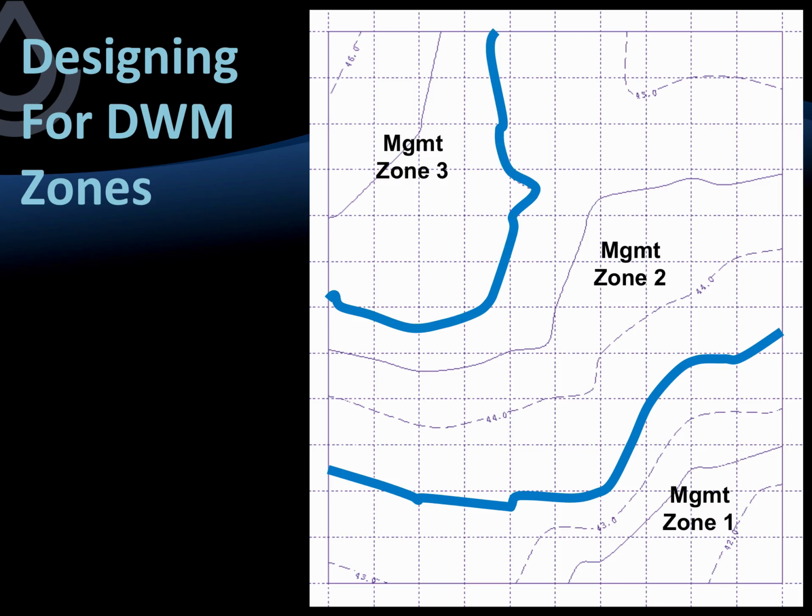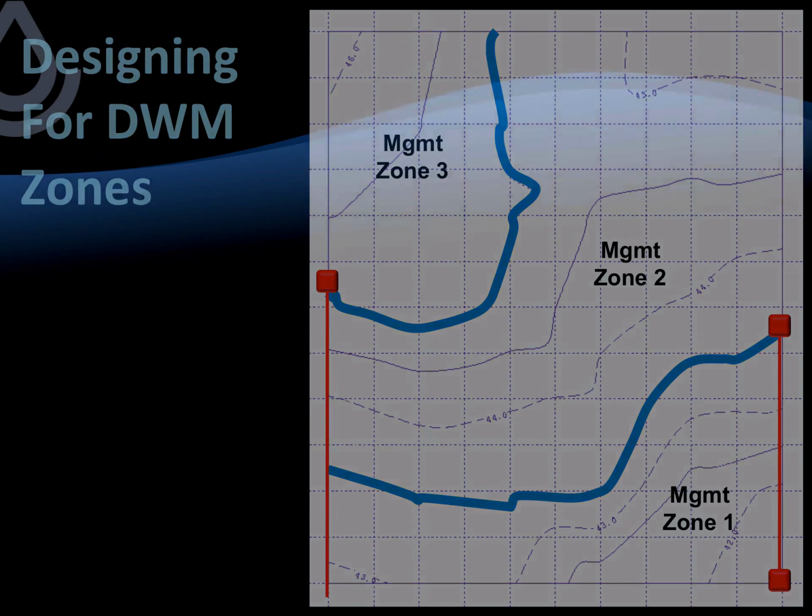And another option here where we break the field into 3 1.5 foot zones. 3 zones here. So a significant aspect to planning these systems is figuring out what the field is giving us. Remember, we're trying to balance the size of the zone with the size of the elevation interval. Trying to reduce the elevation interval where possible and try to increase the size of the zone where possible. And here's one scenario for locating structures for this particular plan.